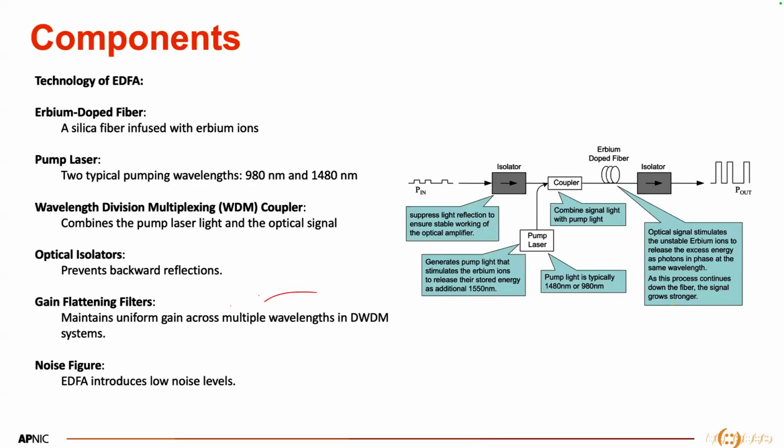Then the laser pump is used to pump the lasers. Then the WDM coupler is used to combine the excited lasers along with the incoming weak signals. They mix together and come to the metastable state E2, and that is how the excited photons lose some energy and the weak signals gain some energy. That is how the weak signals are amplified or boosted.